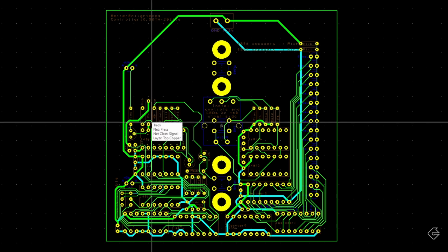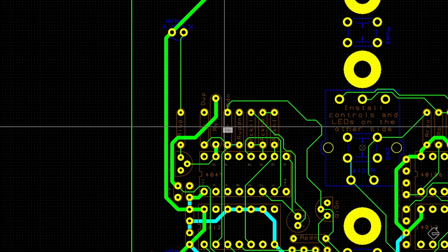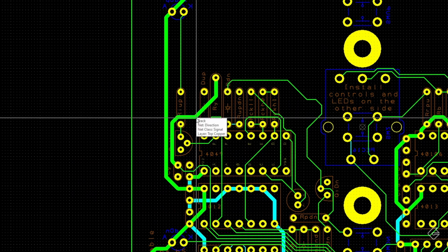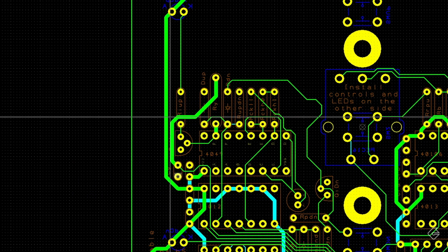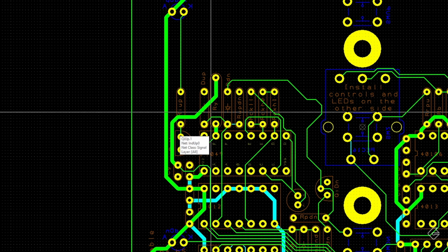And you'll notice a couple of things. One, the trace is thick. And that's deliberate. We want to make sure the trace between RY and CY, the resistor and capacitor, is nice and fat. We have no hindrance of any sort.